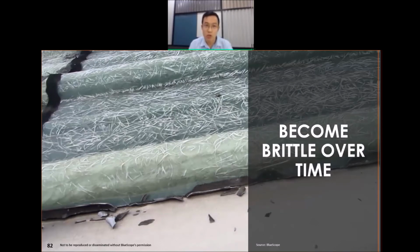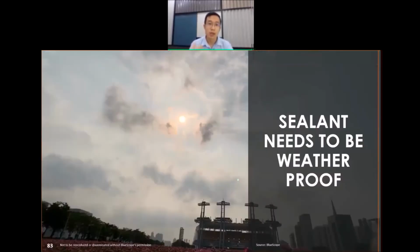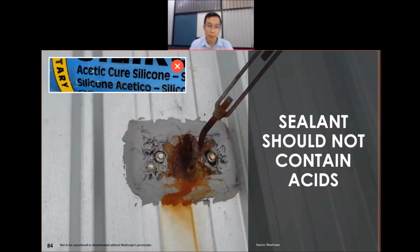So you need to pay attention to what types of sealant you are using, as well as whether it is waterproof enough, weatherproof enough. Okay, so typically for external cladding, you need the sealant to be weatherproof. I think this goes without saying. But another thing that is not commonly known is that sealants can contain different substances. The one that contains acids should not be used in conjunction with metals or steel cladding specifically.